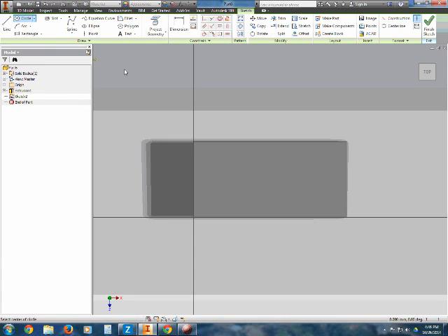Okay, I'm going to grab the circle tool and just click drag the circle, type in its dimension of 4.8, press the enter key, and then you can either right click and choose OK or press the escape key to get out of the last tool, and grab the center and drag it down roughly where it's going to go. You'll see it says we need 2 dimensions. It's a light blue, so that's one thing that tells us that it's not fully constrained. This is the other thing. We need the distance from this edge to the center and from this edge to the center.